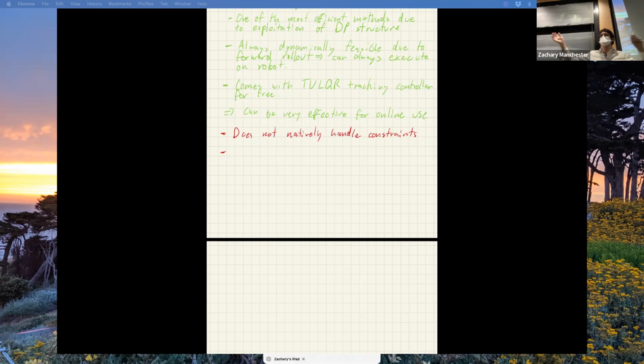You can make up a state trajectory that doesn't obey the dynamics and kick the solver off with that as a guess. That can be super powerful, actually. If you have a sample-based planner or some heuristic for generating guess trajectories that are just kinematically feasible, say, that don't obey physics, you can use those in a collocation method, and they might be really close to the right answer, right? You can't do that here, which can be a huge disadvantage sometimes.